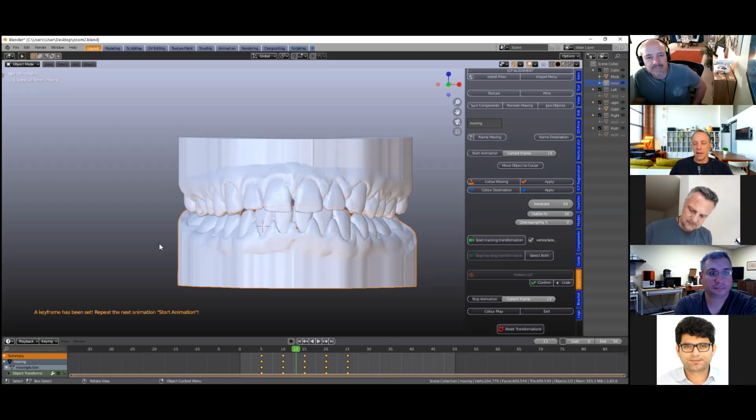You don't have to modify those components, because some of them have undercuts or cementable ridges, and you can't just do a Boolean cut because those ridges will still stay behind and you won't be able to press fit that component into the guide sleeve. So you've got to actually take those out, and we'll have those cutting tools pre-made, which is good.